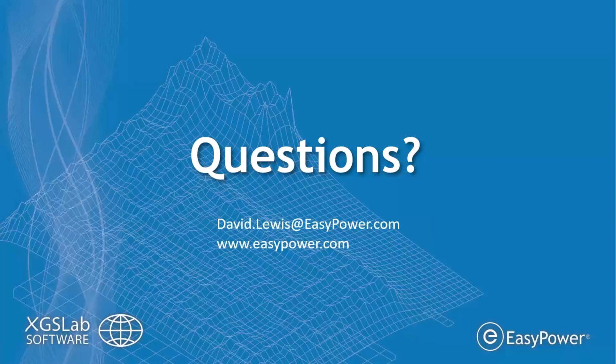The first question I saw is, how does the IEEE 2778 guide for solar power plant grounding differ from IEEE 80, or do they need to be used together? Really, they need to be used together is how I would respond to that. IEEE 80 is what's going to drive the compliance criteria. There are practices that would be typical for a substation but atypical for a photovoltaic system, and that is where 2778 is going to help you.